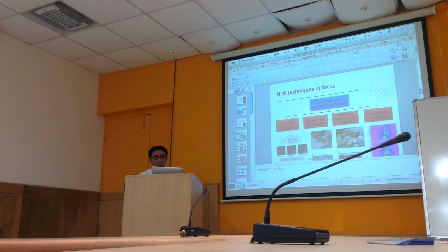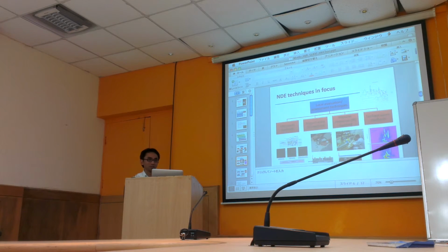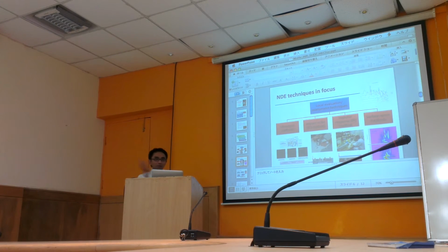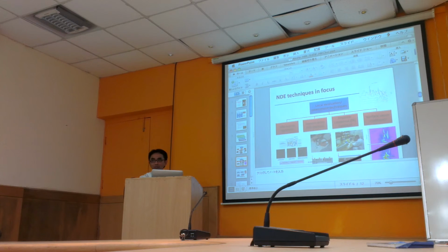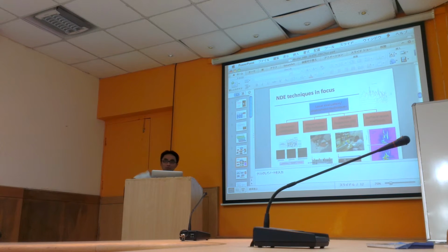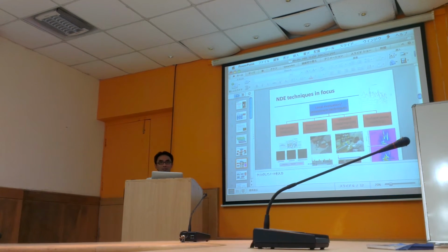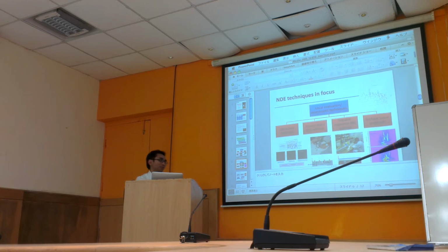It is basically used to monitor structures, for example, bridges. Attach the sensors to the bottom surface of the bridge deck, then wait for the traffic to come. You monitor it for, for example, a few hours, up to 24 hours. Collect the data. The data is in the form of waves, vibrations. And we carry out analysis. From the waveform that we capture, we can analyze it and characterize the damage level, for example. So this is the basic principle of acoustic emission.